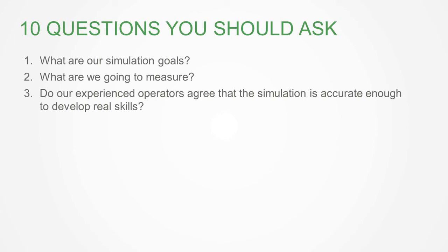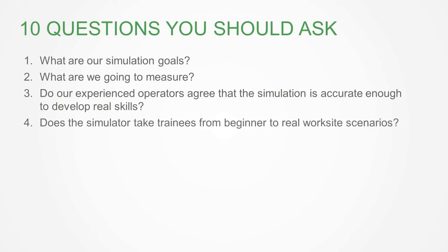Do our experienced operators agree that the simulation is accurate enough to transfer real skills? So the idea of the machine fidelity: get a trusted operator on there. Get them to say, does this give any false sense of confidence? Will a novice operator get on there, get an easy win and say, I got this? What we're hoping is that simulation evolves into the idea of transferring humility and a respect for the machine. So get your operator on there and put it through its paces. Ask the difficult questions on whether these things are going to be simulated well.